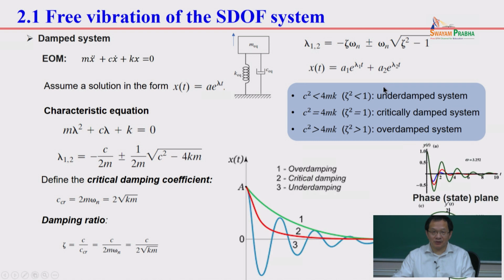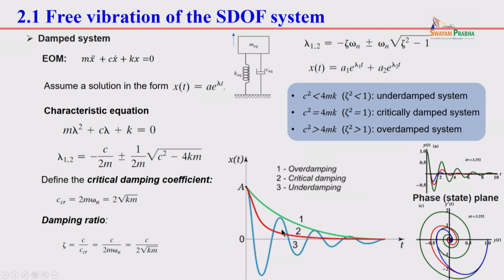So for a vibration system, you look at it in the time domain like that. If you have an under damped case, the blue color, you have vibration, right? And for the over damped case, there's no vibration, it just decays, right? The real line shows the critical damped case. The critical damped case usually gets to 0 faster than the other cases.